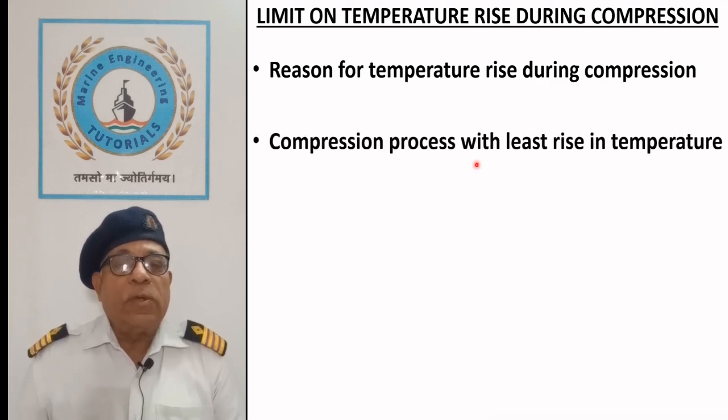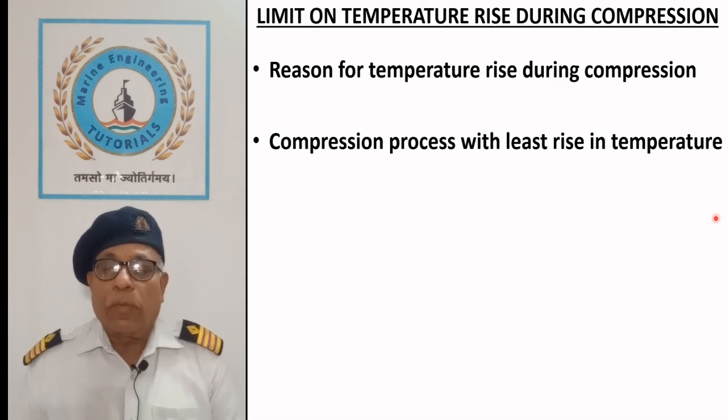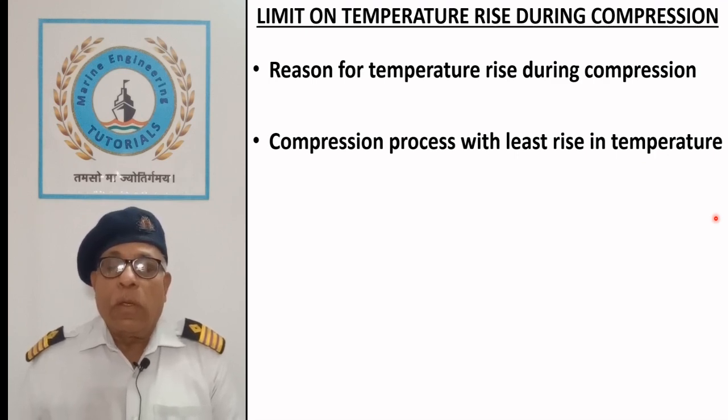Compression process with least rise in temperature. As discussed earlier, isothermal compression requires least work of compression. Although it is impracticable, we still aim to approach it by taking away the heat from the cylinder and its cover, in addition to cooling the air after its compression before it is sent for further compression.